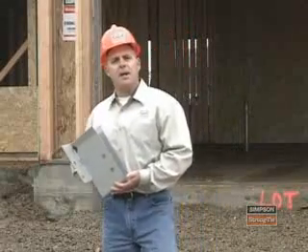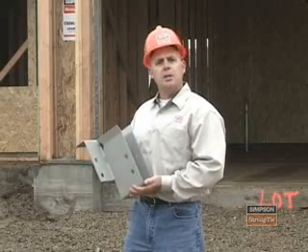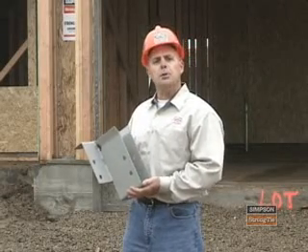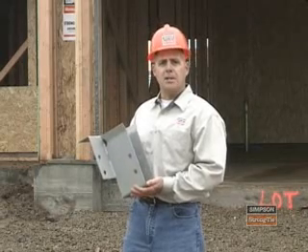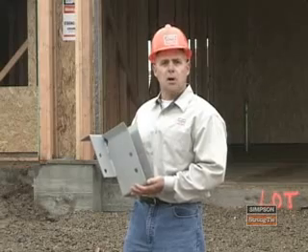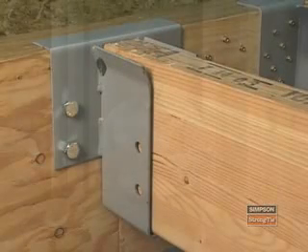Beam hangers are typically heavy-duty connectors, which may require the use of screws or bolts. Just like with joist hangers, there may be times when you don't know which beam hanger to use. If this happens, don't install a hanger just because it's the right size. Doing this can cause life safety issues. To install a beam hanger, follow the joist hanger installation process. Note, however, some important differences.